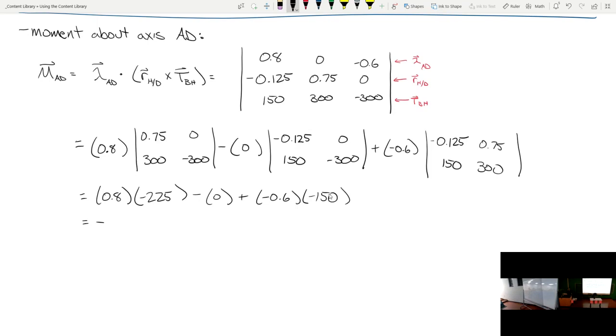Thank you. All right, so what do we get at the end here now? So this is going to be positive. This is going to be negative, but I think it's going to be negative at the end just based on the magnitudes. Do I have an answer? 90. Do we have a second? All right. I got 90 at the end, but I didn't do the intermediate steps. So therefore, the moment about that axis is negative 90, and in this case, it's Newton meters. We don't use the term joules when it comes to moments. We just write it out as Newton meters.